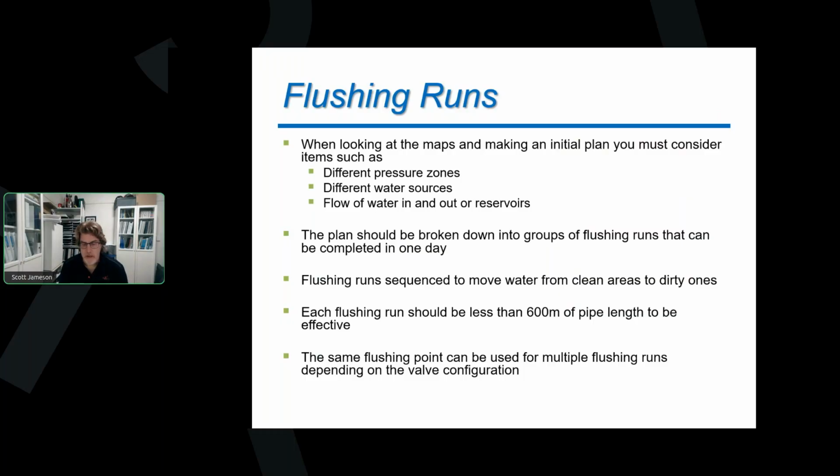Maybe I can only get 2 or 3 runs done in a day because I have to go back and forth so often to the valves and to the hydrants that I'm flowing from. It might also be a limit of your water capacity, right? Maybe your reservoir doesn't have enough capacity to do more than 1 or 2 flushing runs a day. So I need to limit myself that way.